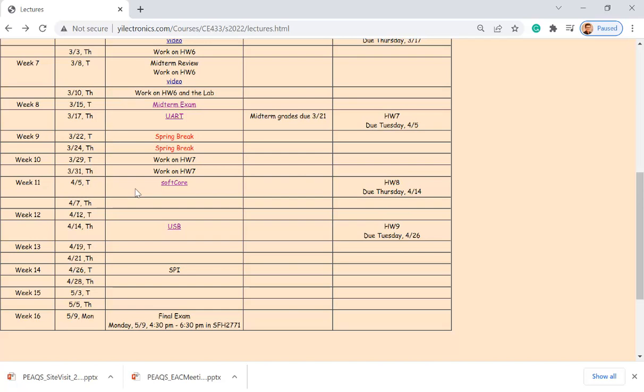And what do they do? So the ARM core is a module. They have that module loaded, like adding a source, right? Adding the source to the design environment. And it has a name for the module, like ARM Cortex-M7 or something. And in their top module, which is the whole chip, they just instantiate the ARM core in there and have all the pins. There will be thousands of pins, not like the 5 or 6 in your example, thousands of pins, being connected to other modules in the top. And you may have memory files as another module you have to instantiate, so you have to declare wires to make the interconnections. That's how they design SoCs.